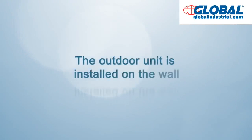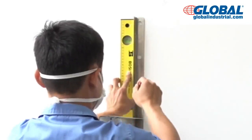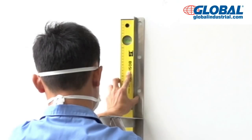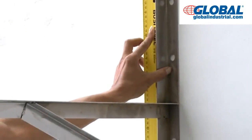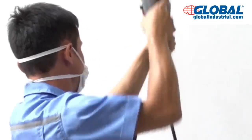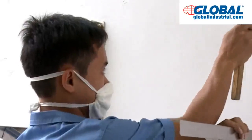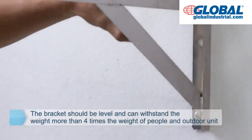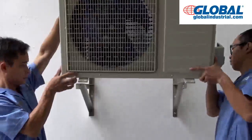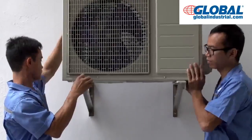The outdoor unit is installed on the wall. Confirm the position of bracket holes with level meter. Note that bracket should be in a vertical plane. Fix mounting bracket of the outdoor unit. The bracket should be level and can withstand the weight more than 4 times the weight of people and outdoor unit. The outdoor unit should be placed levelly on the mounting bracket.